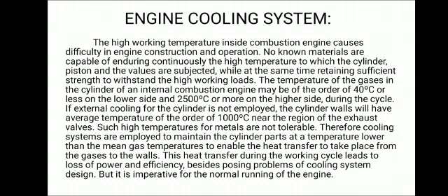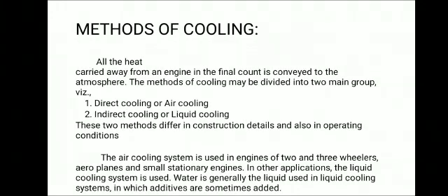The temperature of gases in the cylinder of an internal combustion engine may be 40 degrees Celsius or less on the lower side and 2500 degrees Celsius on the higher side. Such high temperatures are not tolerable. Therefore, cooling systems are employed to maintain the cylinder parts at temperature lower than the mean gas temperature. Methods of cooling: they are direct cooling and indirect cooling.